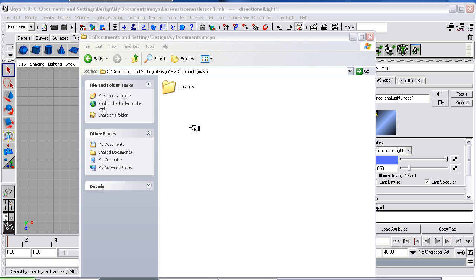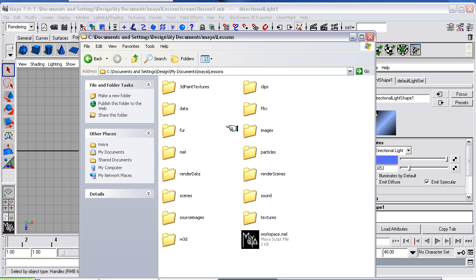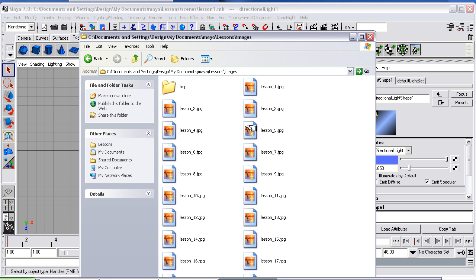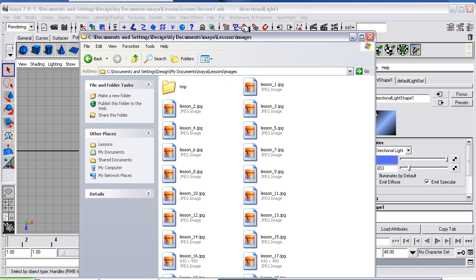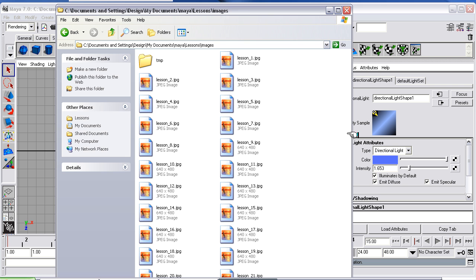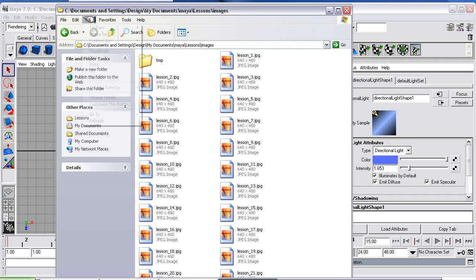Hello, well if you watched the last lesson, the last thing I did was batch render a simple animation that we've done. So now I want to show you where they are. If you go into your Maya folder, which we talked about I think in the first or second lesson, then you'll see that they're in the lessons project, the one you just created, there's an images folder. Click in there and you'll see the rendered result of the images that you just rendered.